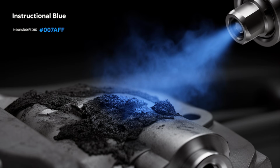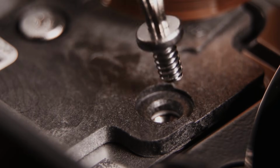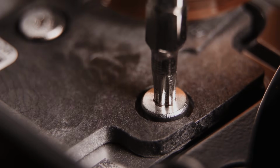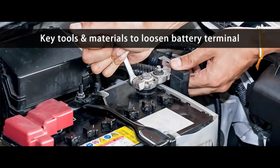Do not substitute brake cleaner, carb cleaner, or generic electronics spray for dedicated MAF cleaner. The sensing element will be permanently damaged and the sensor will require full replacement, typically $80 to $180 for an OEM unit. The removal process. The MAF sensor on the vast majority of vehicles is secured by either two small Torx screws or a single plastic retaining clip, depending on the manufacturer and model year. Before touching anything, disconnect the negative terminal of the battery, or preferably, use a memory saver to preserve your radio presets and ECU adaptive data temporarily.